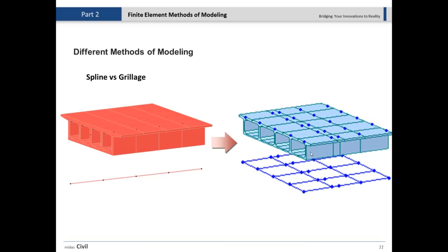If you can imagine that you want to bend this one in the x direction, out of plane, it easily can rotate, right? If it's just one of these girders right here. But if you keep them all together, definitely we have a larger torsional bending stiffness in the out of plane directions. So that will be guaranteed as well.